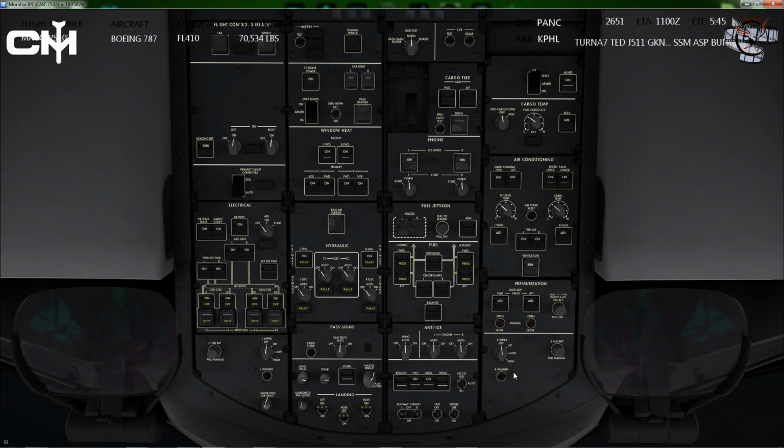So if I go back to the start of this on the checklist here, I can just basically literally go right down the list. So passenger oxygen light, oh, that's not even the right, I gotta go back on another page. There's so much stuff here. Flight control surface panel, tail switch, wing switch, both normal. Heading reference switch is normal. Primary flight computer's disconnect switch has the guard closed.